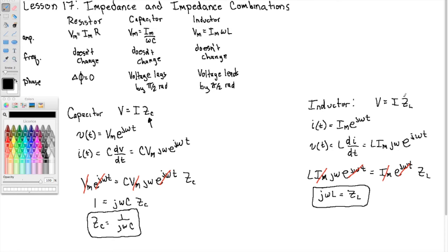So this says I can, in fact, express the voltage and current algebraically, so I don't need to use calculus, but the trade-off is that this thing that's playing the role of the resistance, ZL, is imaginary. It's j omega L. So our choices are to use derivatives and integrals or to use complex numbers. We're going to choose to use complex numbers.